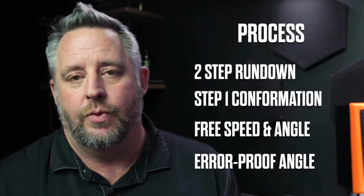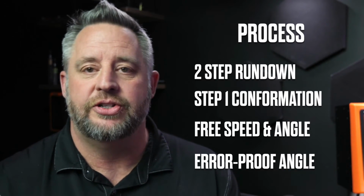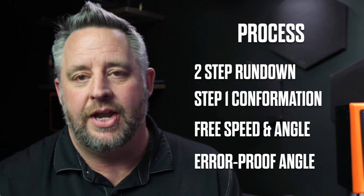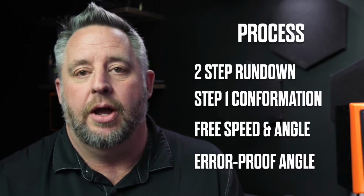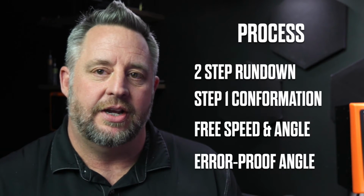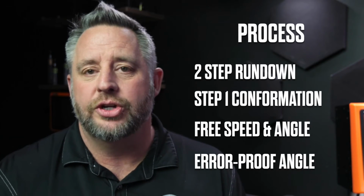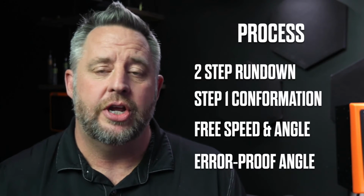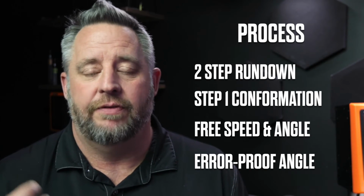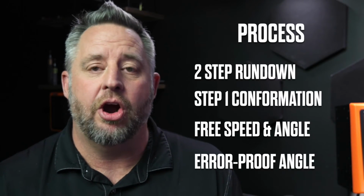Once we get through most of the fastener, the tool will then downshift to its seating RPM and run down for the torque that it is designed for. And that's basically for a lower torque value. We don't want to create any additional inertia by having a fast RPM. It'd be very, very similar to if you're driving in a car.